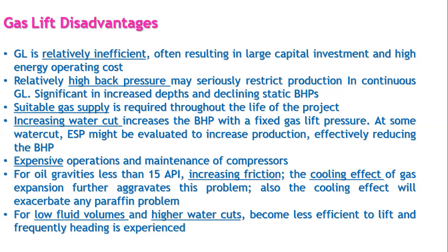The cooling effect will also exacerbate any potential paraffin problem that we have in the well. So those considerations should be really taken into account before the company decides to go for this system. For low fluid volumes, high lift is not the most efficient type of artificial lift.